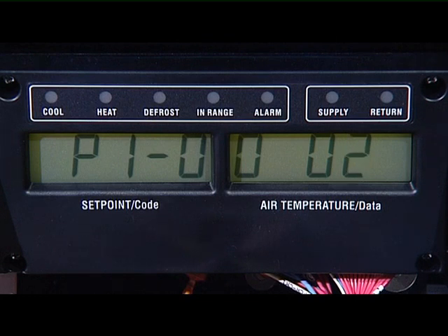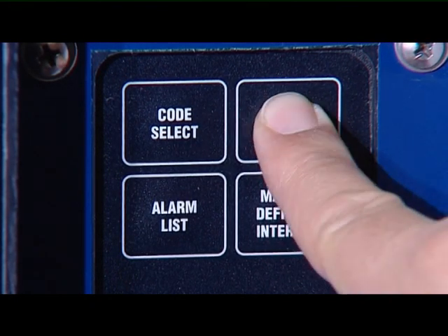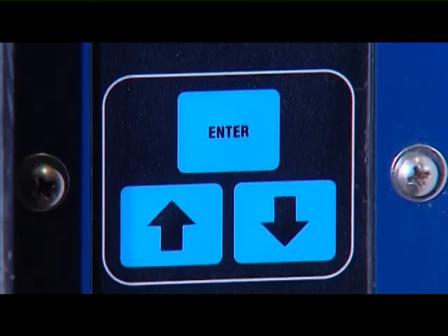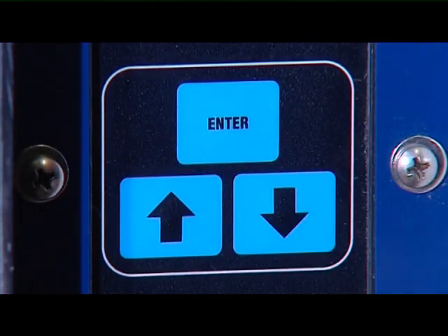When an automatic test fails, it will be repeated once automatically. If the repeated test fails again, the unit will remain in standby until the next input. An automatic pre-trip inspection is started by pressing the pre-trip key and then the Enter key.